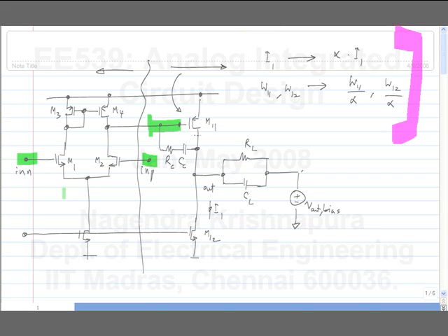The contribution of M12 to noise, it will contribute noise directly to the output. That's correct. But if you look at M1, it will contribute noise here, and that gets amplified by M11 and goes to the output. So the contribution of the first stage is much more significant. The same is true for the offset. So the expressions for noise and offset will be the same as that of the simple differential pair, plus you will have an extra term because of M11's noise getting divided by the entire gain of the amplifier. So do we need to discuss this further, or is it clear? This noise stuff.